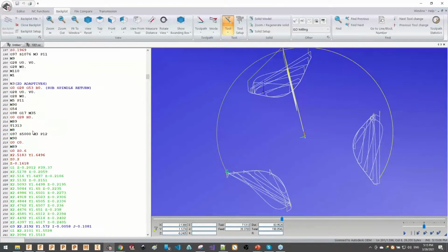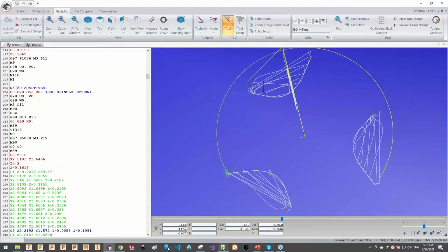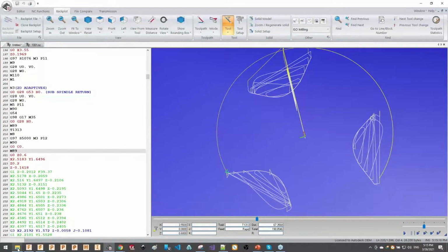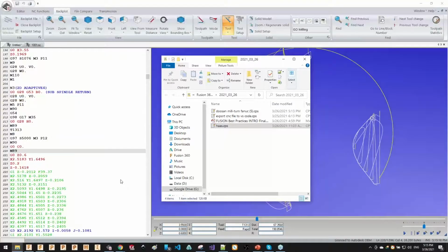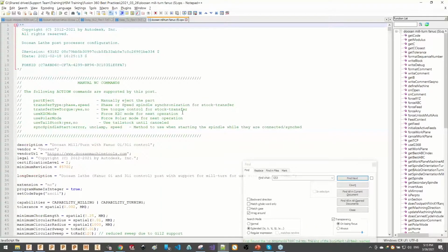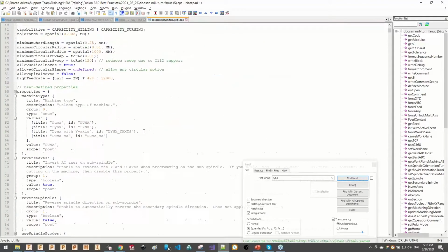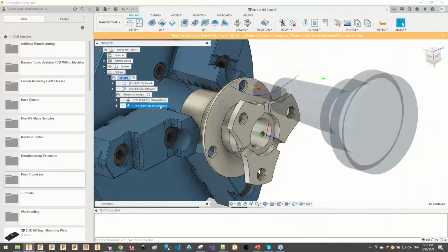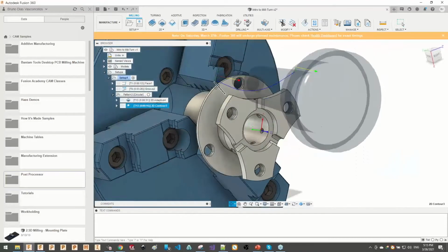Even though the post processor understands, because in every single post processor there is something that tells what's the range of your machine. I can show you where that is located. And what the post engine does basically, it sees if that operation is within the range of the machine, it will use the X and Y. But sometimes, maybe due to a little line that is out of range or something, that could be not 100% valid.